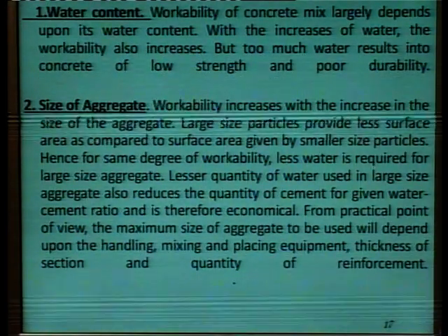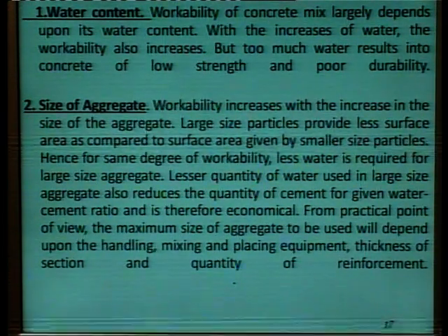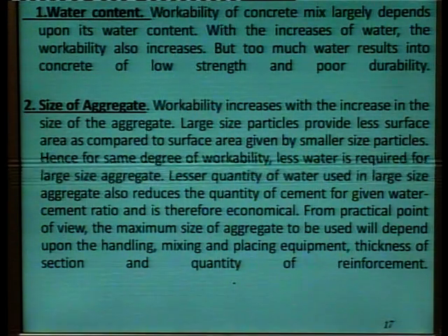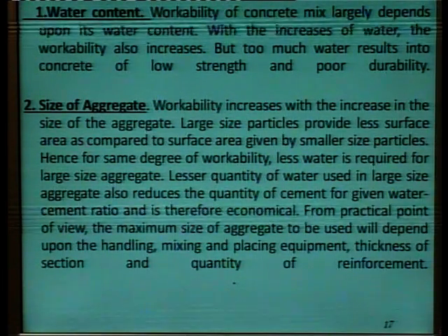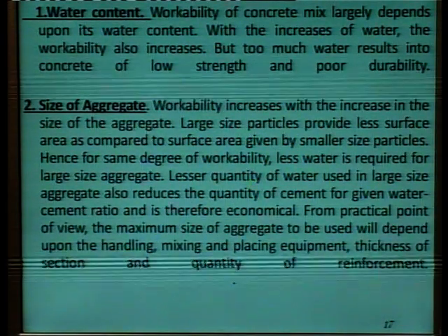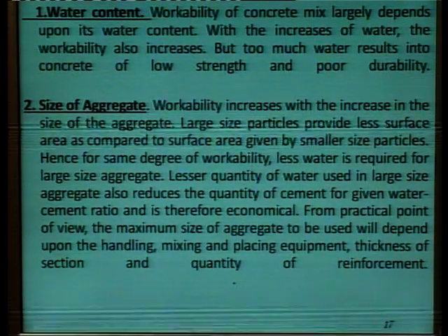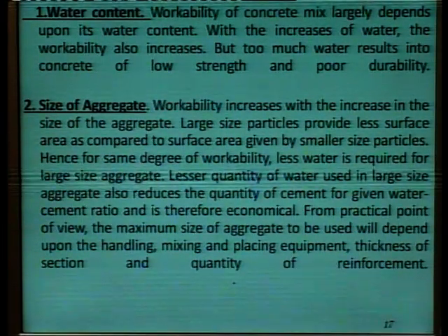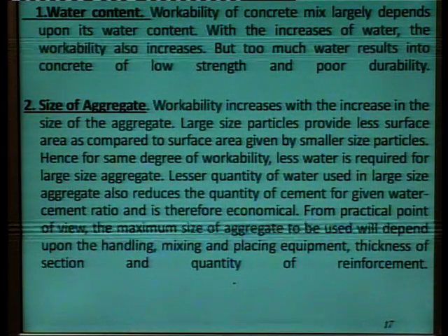So, first is water content. Workability of concrete mix largely depends upon its water content. With the increase of water, the workability also increases, but too much water results into concrete of low strength and poor durability. Second is size of aggregates.